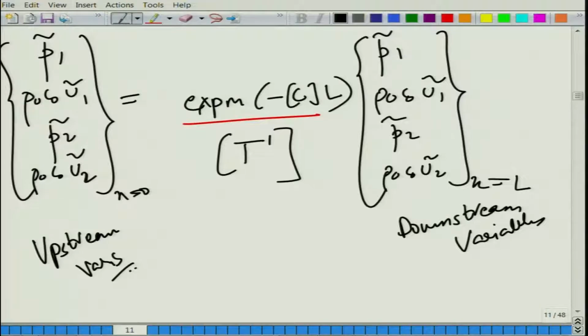Now, having denoted this matrix as T1, we probably would want to reshuffle a few things, because we are trying to follow the convention available in the literature regarding plane wave analysis of concentric or perforated mufflers. As a result, what we would like to do is reshuffle the matrix.